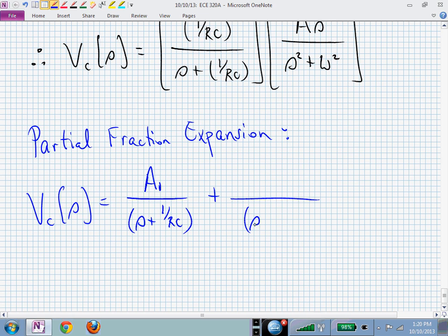And now I have the pieces due to my sinusoidal excitation. Even though I applied a cosine, it may start looking like a combination of a sine and a cosine. Or you could say a cosine with a phase shift. That's the same thing. They're equivalent. So you could say, oh, I just have a magnitude and a phase associated with this cosine waveform. If I now put this as a B1 and I say this middle term I want to be associated with my cosine, what do I put in the numerator in addition to B sub 1? I need to put an S.